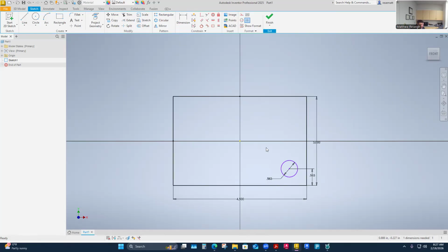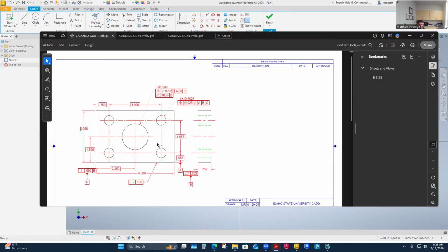Let's see. And then it's over 3/4, I think, but it's really from the other direction the way it's dimensioned. So I'm going to kind of do that. What I'm looking at is I'm actually using this dimension to place it, and then I'm going to use this dimension. It's really 3/4 and 3, so I'm going to say it's 3 3/4 from this edge over to there.